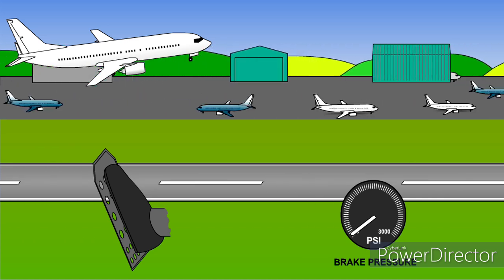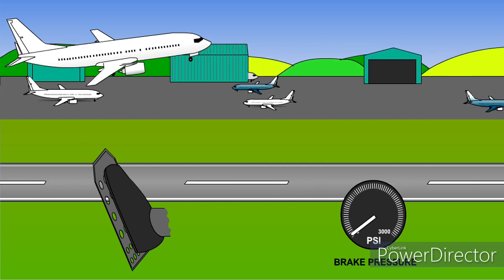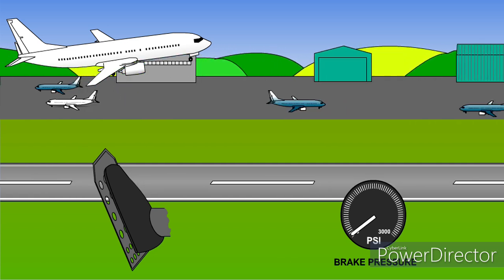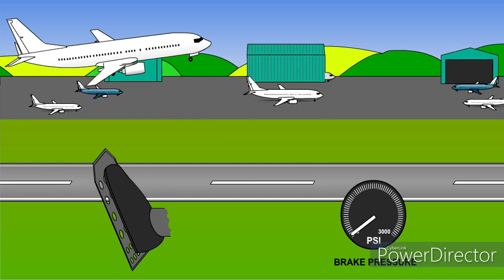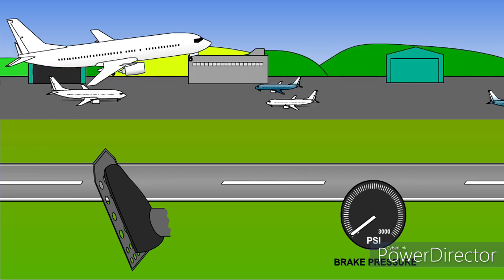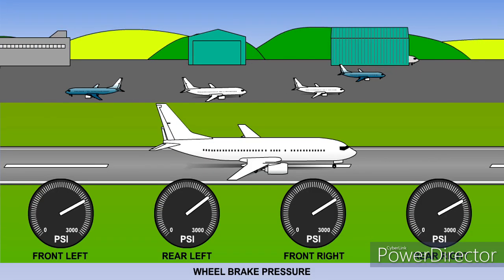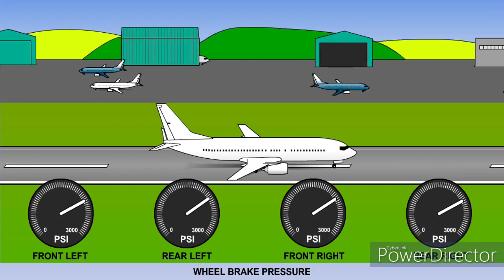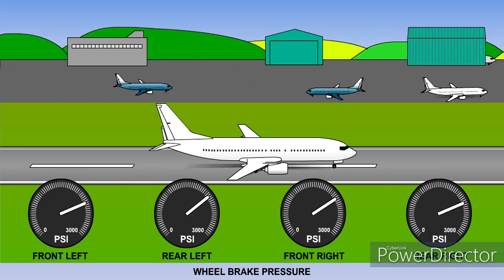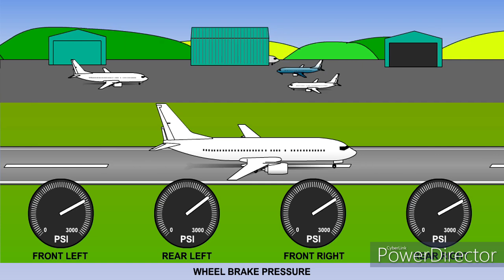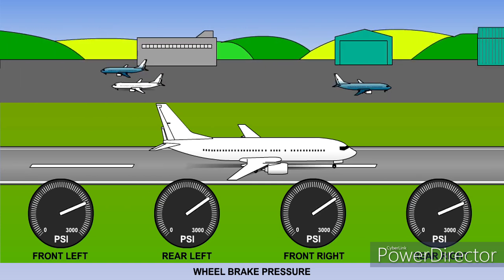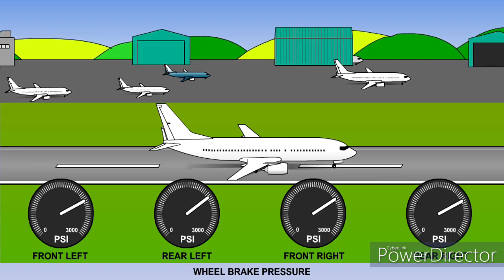On touchdown, the wheels spin up and apply a signal to the control unit, which will now allow the brakes to be applied. This does not, however, imply that you should attempt a landing with the brake pedals depressed. It is a safety backup system only. For skid prevention, the anti-skid control unit will reduce the brake pressure to any wheel that it determines is approaching a skid by monitoring the deceleration rate of the individual wheels. It will then modulate the pressure to ensure optimum braking.